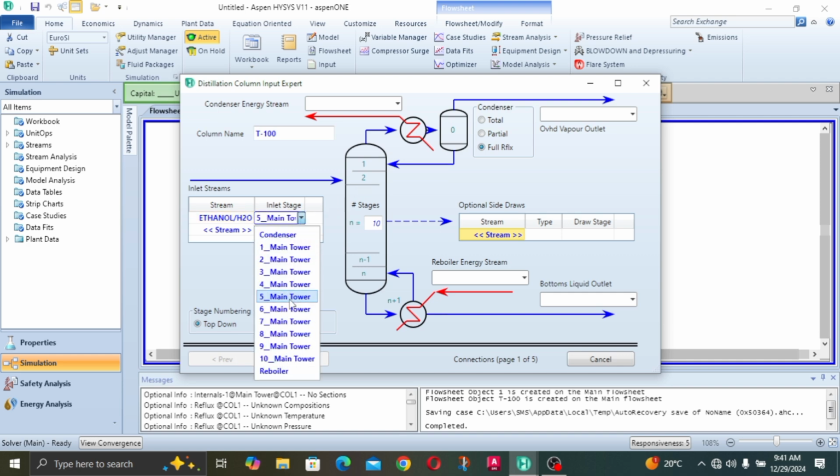By default, it's on the 5th tray, maybe somewhere around here. And then that works perfectly fine. But remember, we said it's a thing of research. For a more efficient separation, you tend to do more research to know what works best for your process to make it more efficient. But we could just stick with the 5th stage. That would do the work for us.